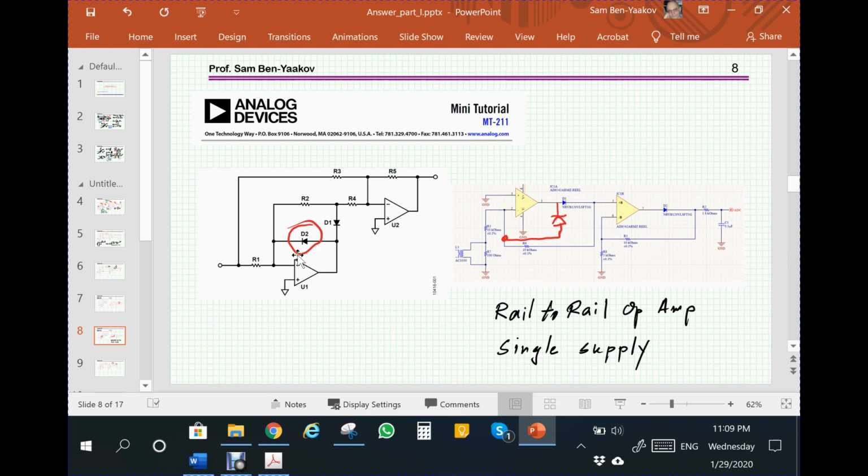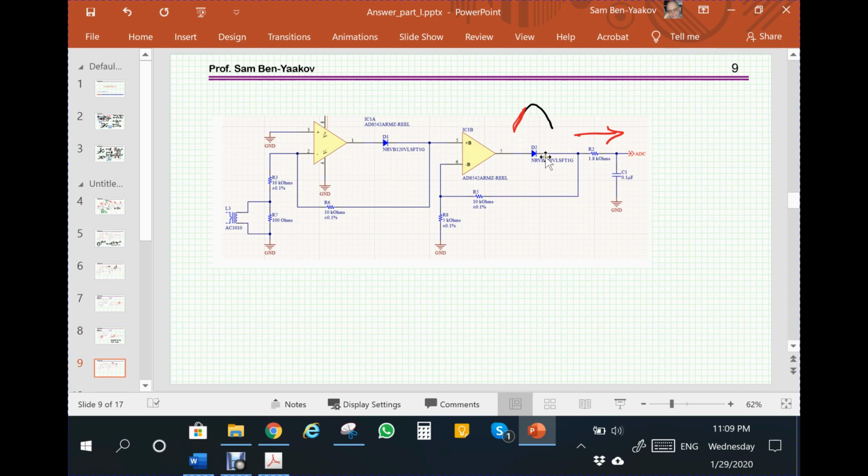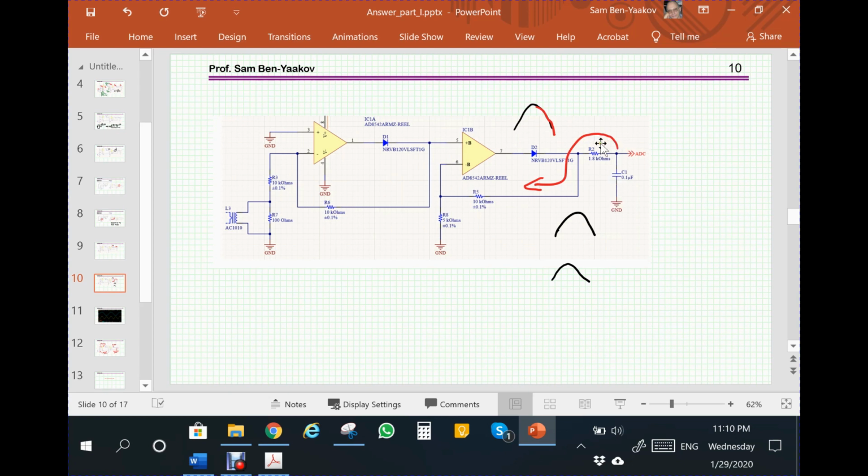So this is another issue here, that there is no diode in the original design, and it's really highly recommended to have a diode. And then we come to the filter point. Now, this filter is now fed from this amplifier, but with the diode, which is not needed, but it's given here. Now, during the time that the waveform is sort of riding up the positive slope, the diode is conducting, charging the capacitor. Now, what happens as the voltage goes down? In this case, the capacitor has to be discharged.